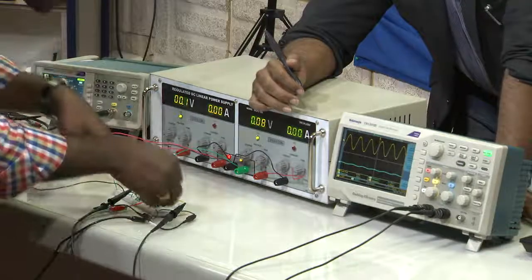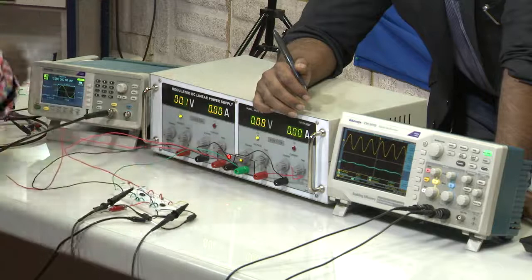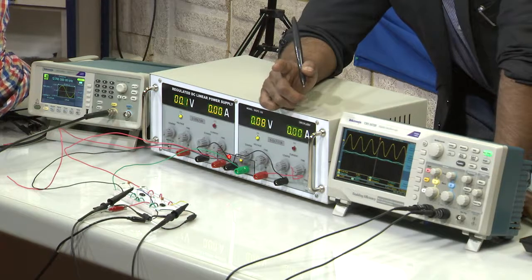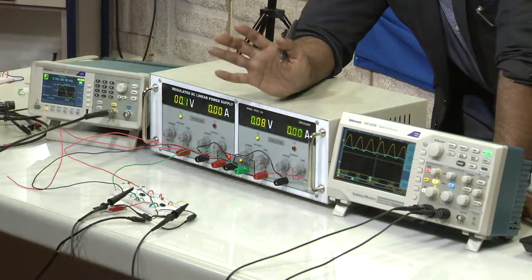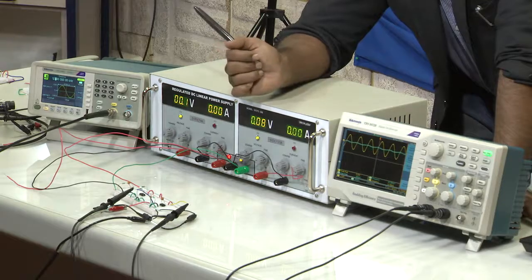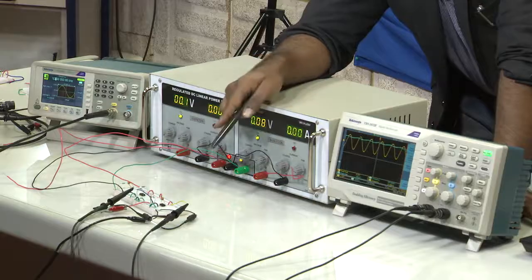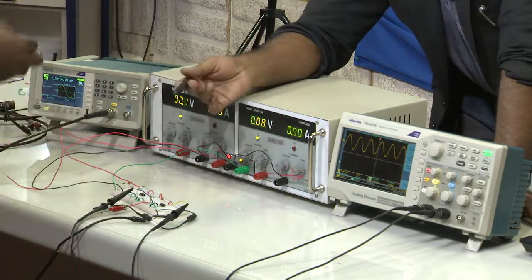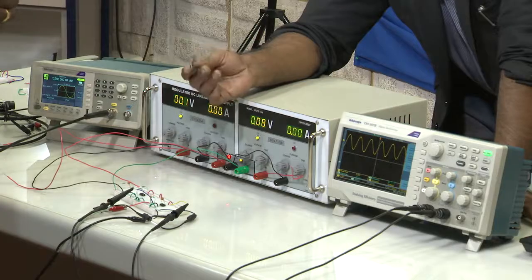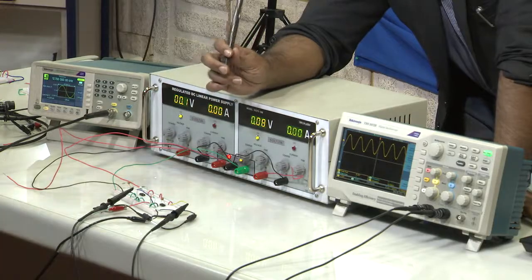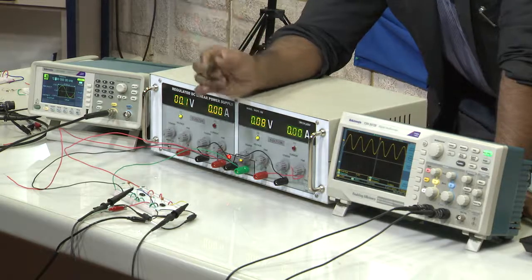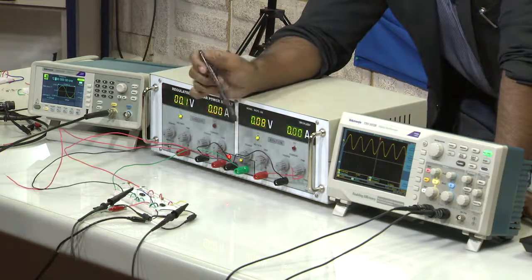He has to get another resistor, because we want a gain of 1, but if you do not have one, that is fine. What is the value of the resistor that you have? 10k, and another resistor 10k. Then we have a gain of 1, but the cutoff frequency will be the same. Do we have another one? 5 minutes, I will get it. That is fine.